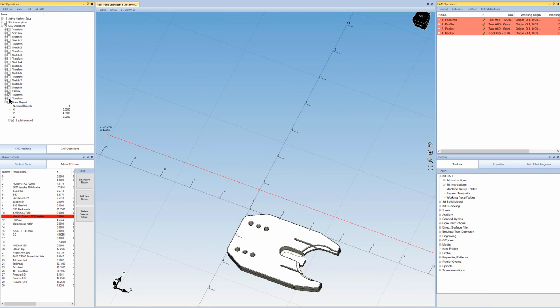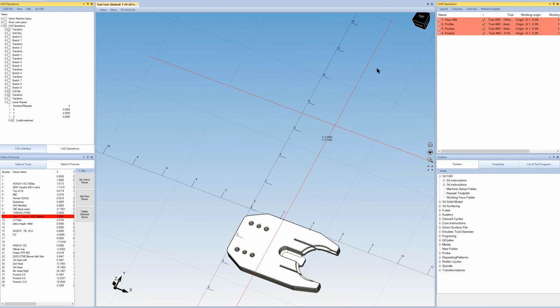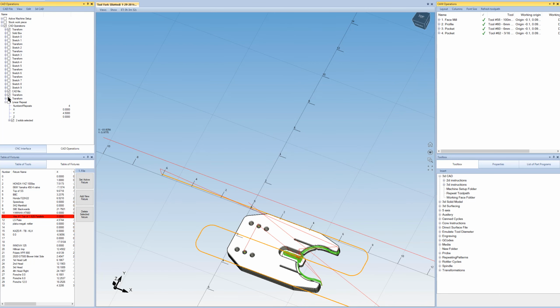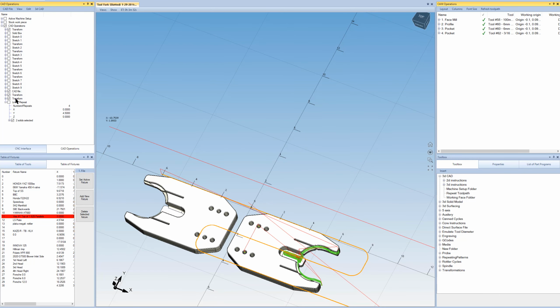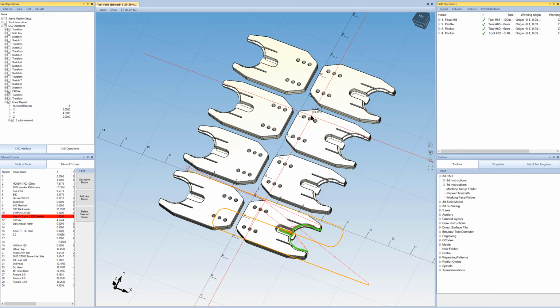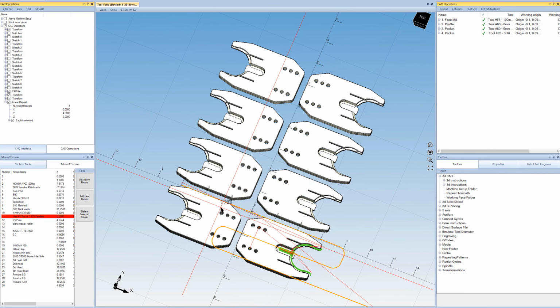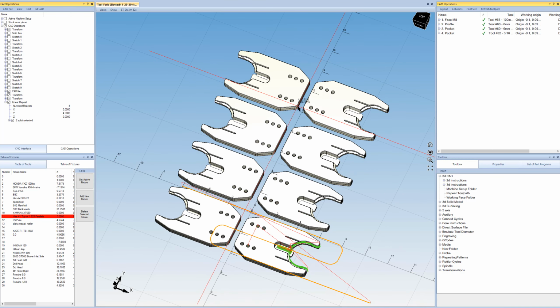So over here on the CAD side, we just had one part, and we're going to put all of our toolpaths on that one part. And then we're just going to mirror it over with a transform instruction, and then do a repeat up to the top there. So these are nice, neat, and organized. Everything's rotated to like 90 and 180, and everything's evenly spaced. We could just lay these down however our fixture is made, in any orientation and all of that.